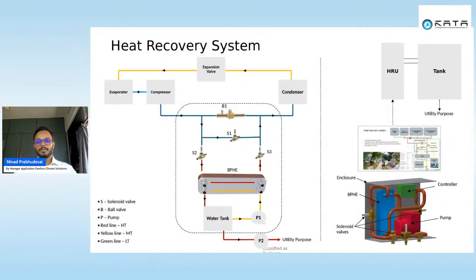Okay, so I think that was all about the heat pumps side. The other topic which I just wanted to touch upon is the heat recovery system. There is a minor difference between the heat pump and the heat recovery system. In a heat recovery system, we are not going for very big condensers, because here we are just using the sensible heat from the refrigerant to heat the water.